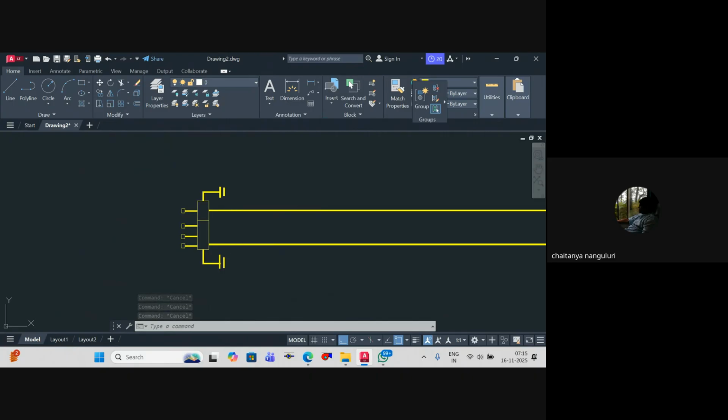One more doubt. Wherever we have got three pressure switches, based on pressure only it goes to the particular pump, is it? Yes. From the pressure switch, you have a setting of switching on and off. So you have a start point, a differential pressure. Your differential pressure switch is what you use. The minute there is a pressure difference, automatically the pump will turn on. So you will set the value. Say, for example, you want the pump to be on at 8 kgs, so you will keep that setting. For off, you don't have any setting anyway, so you need not worry.